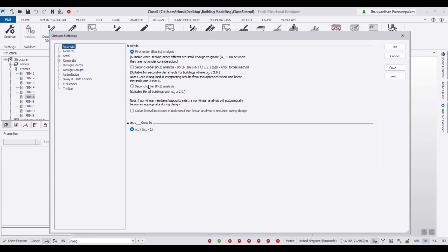If you have a very tall column, 20 meter, 25-meter column and so on, then you have to worry about the slenderness. Our buildings are very stocky, so you don't need to worry. The simple rule of thumb is the height over width ratio: if it is less than 4, then your building is stocky and you don't need to worry.